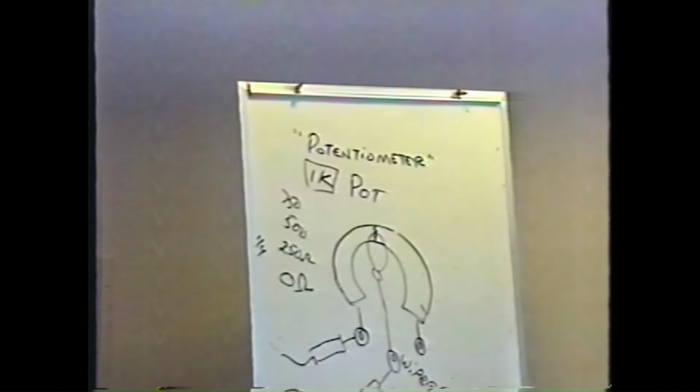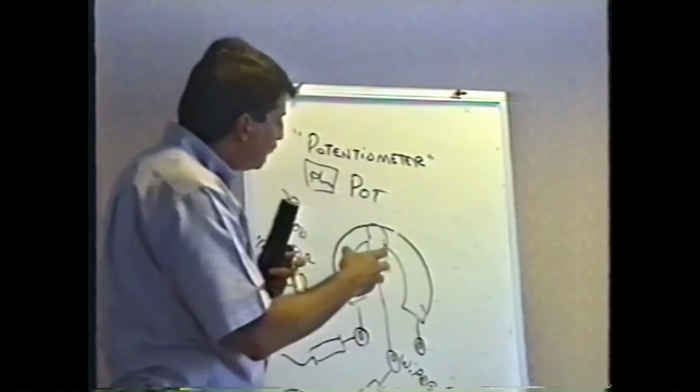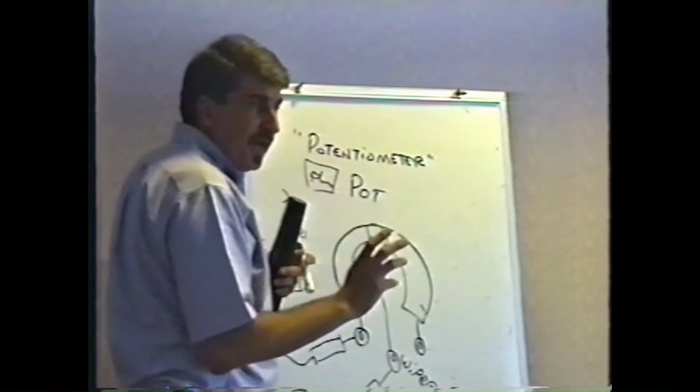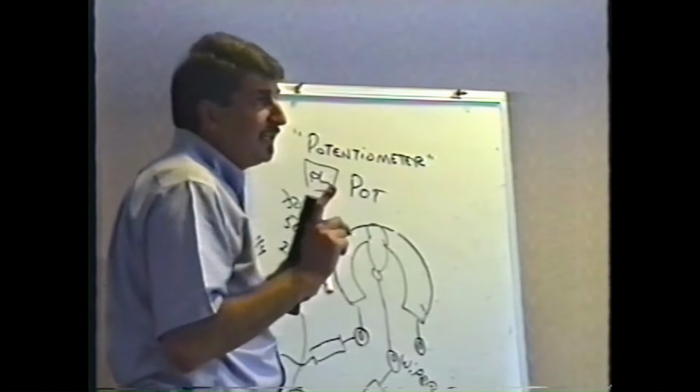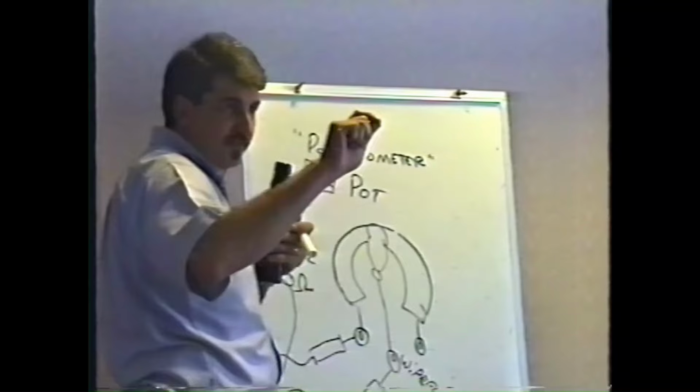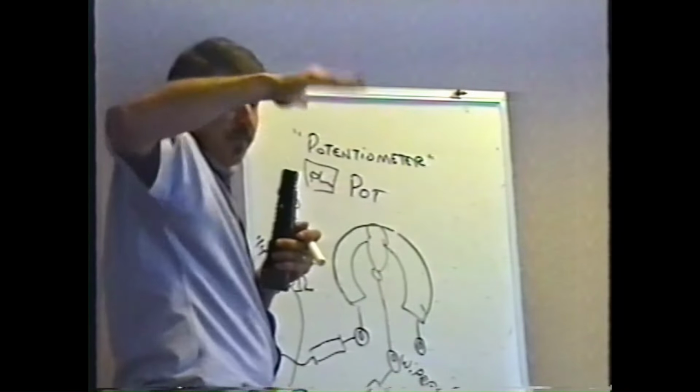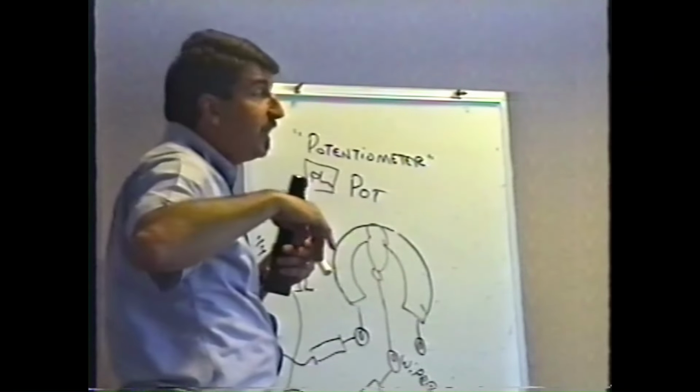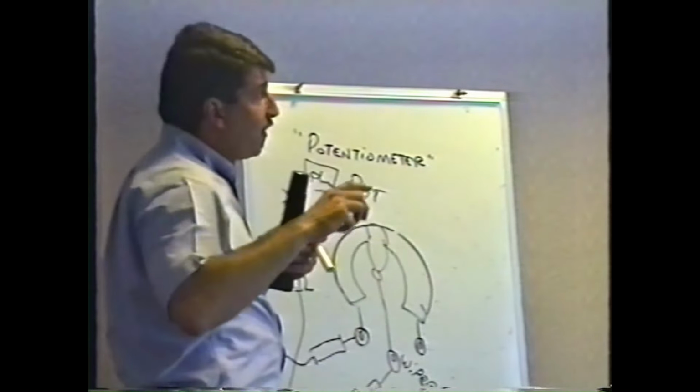They changed those circuits, and modern radios don't do that anymore for reasons that I can't get into right now. But that's when the pot gets dirty. And typically in a game, what will happen is you'll go to adjust the power supply voltage, and as you just barely move it, the thing jumps up and down, the voltage fluctuates like crazy. Or you're adjusting the vertical size control of a monitor, and it just jumps all around like this.